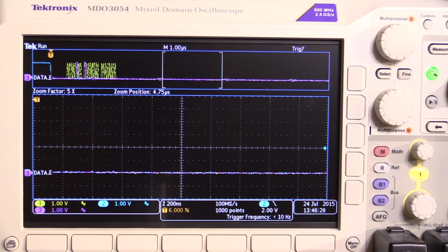As far as using this to control, say, a power supply, which is why I'm looking at this DAC in the first place, I'm not using the Raspberry Pi or whatever microcontroller at this level as an interactive part of the feedback loop for controlling the power supply. I would use it to set the reference levels.